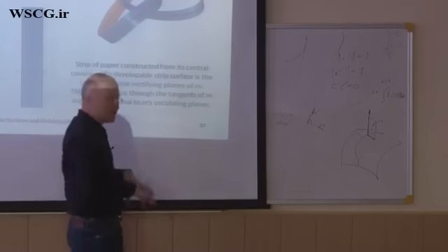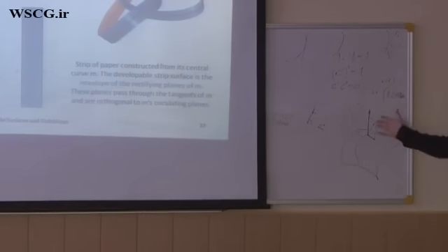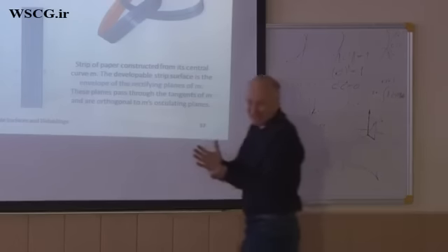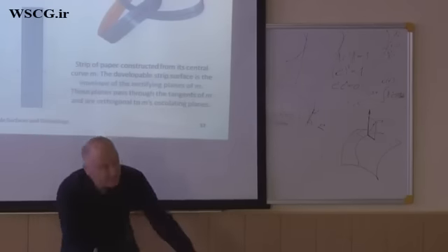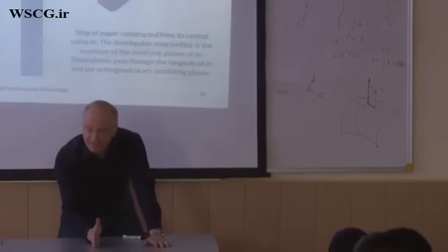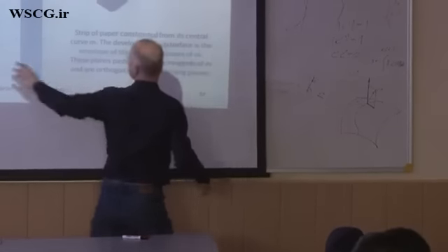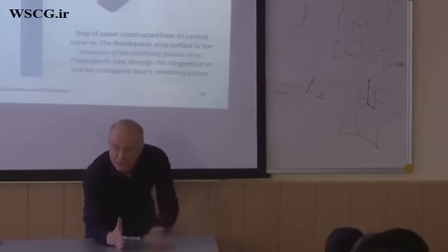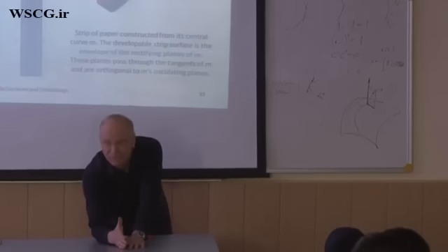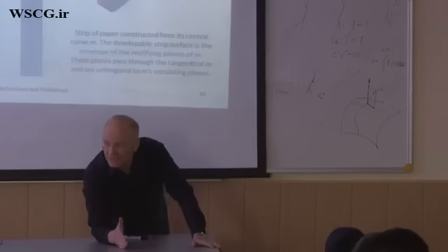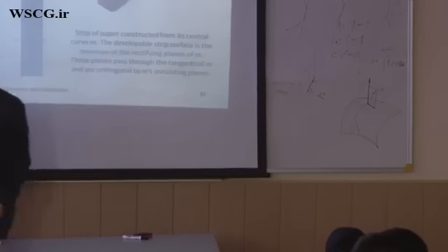So the way to get a straight line in the development is to look for a curve which has vanishing geodesic curvature. What I have said here implies I can only get this vanishing geodesic curvature if the osculating plane of this curve is orthogonal to the tangent plane of my developable surface. And this is why I say if you are given this middle curve, you look at the osculating plane, you take a plane orthogonal to it as a tangent plane of your developable surface, because then you have ensured that the geodesic curvature is 0. So this geodesic curvature is important, and it will pop up.